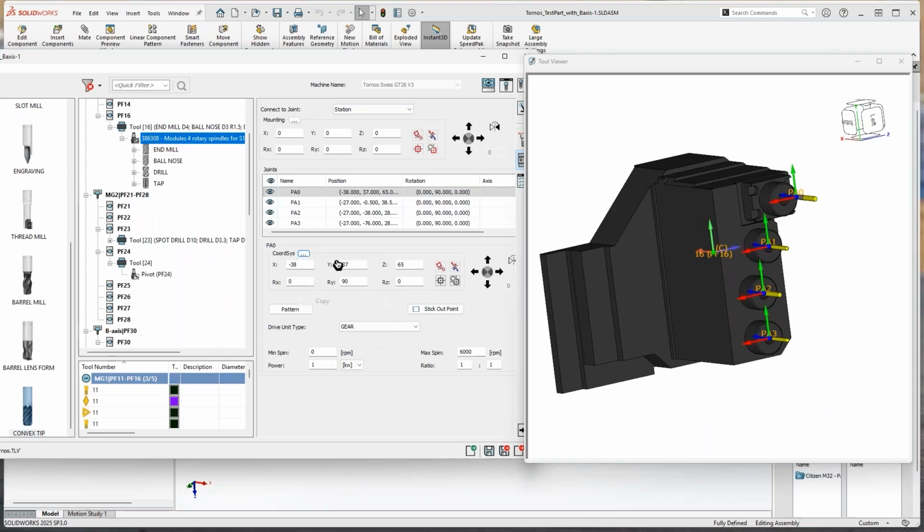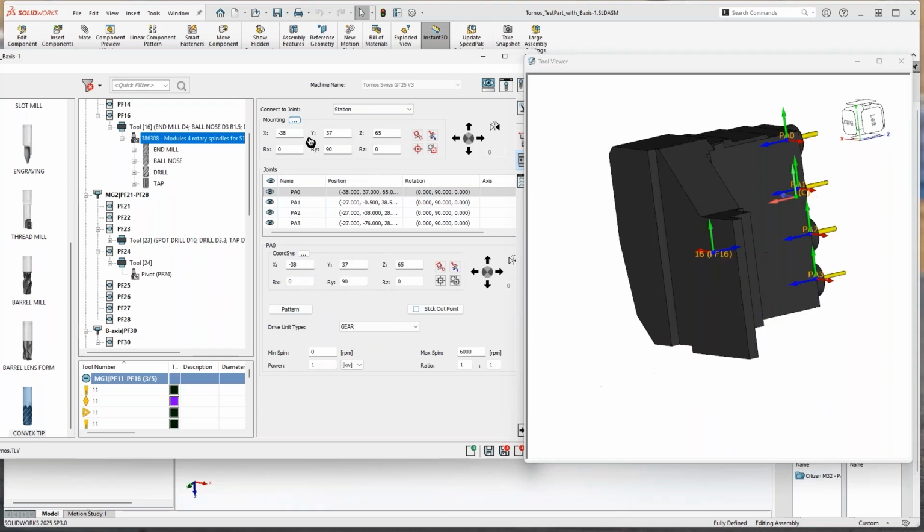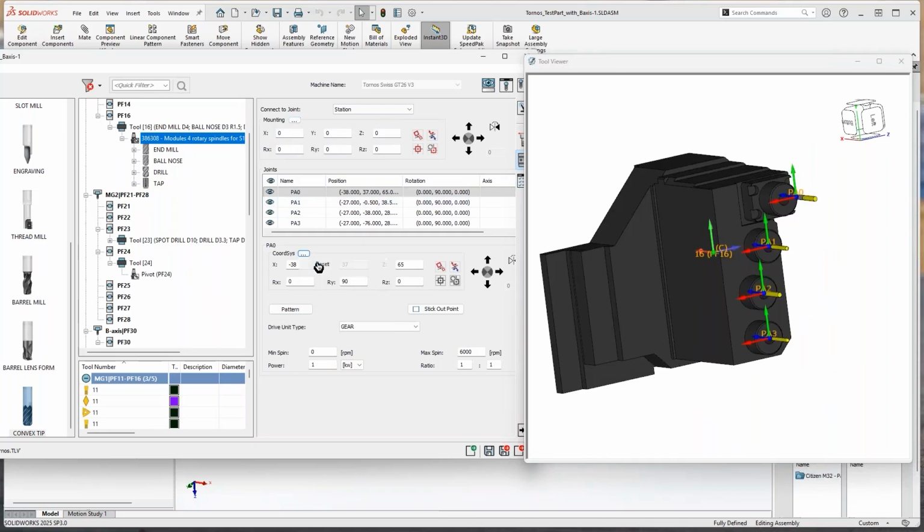So if I now do a copy here, I can go to the mounting and paste here, and all the values that you have in this field can go to that field. Before this, whenever I was adding joints and copying values, in order to bring everything to 0, I was selecting all these fields and typing in zeros. It was a time-consuming process, like 0 tab enter, 0 tab enter. But now we have an option to just reset. It will bring all the values to 0 in one simple click. So I like this one. I really, really like this one.